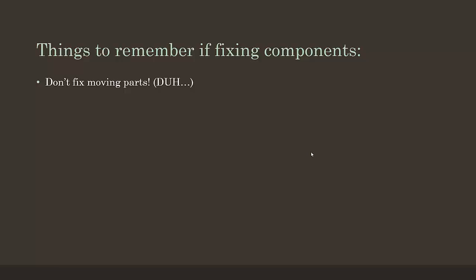Oh yeah, if you had a group of parts that are all together, you could pick them with the Control key or the Shift key, right click, and float them. They'll all update immediately, and then as soon as they update, you can pick them all again, right click, fix, and you're all set.